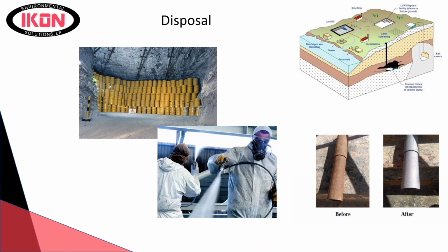And you essentially have unlimited activity. The well has some requirements in their permitting for the Railroad Commission. Their permit's not going to say you can inject 6 million picocuries per gram radium-226 down your well. What they will say is you can mix somebody's 2 drums of 6 million picocuries per gram with 200,000 cubic yards of non-radium impacted E&P waste to make sure that your overall concentration in your well is below that.